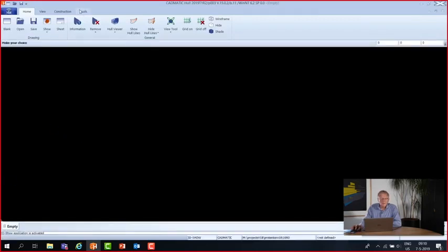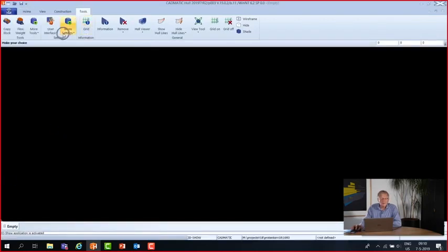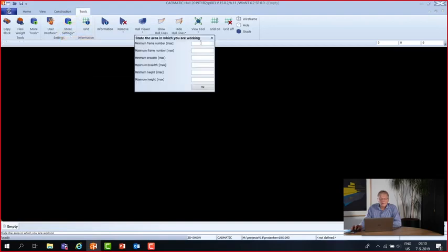Okay, here we are, and I will define an area from frame 24 until frame 41. Minimum breadth 4 meters from center line, minimum height 8,000, and the maximum height 14,000 millimeters above baseline.